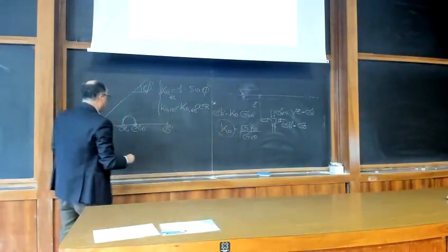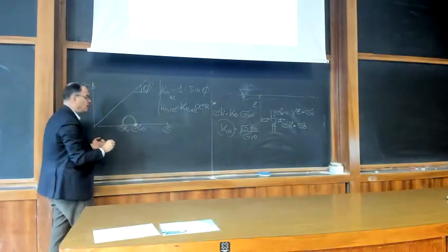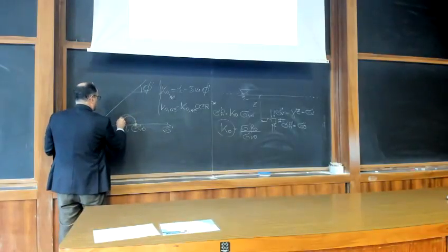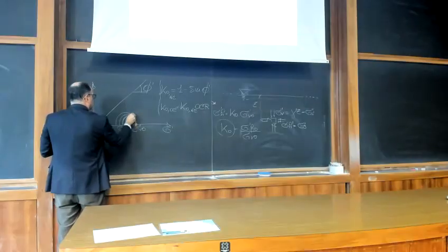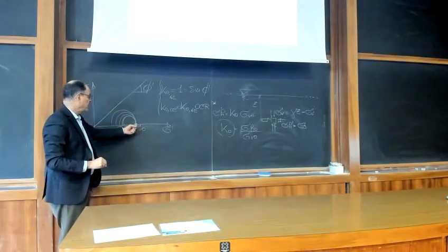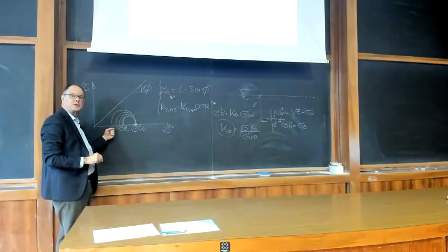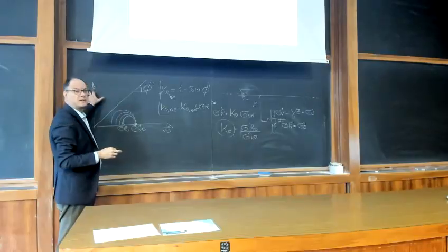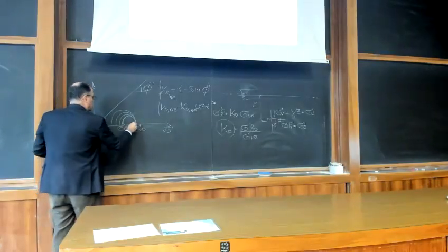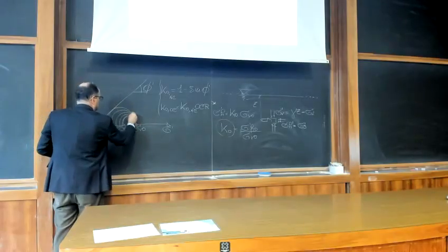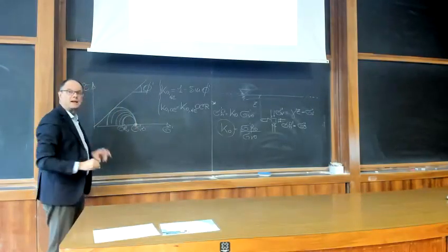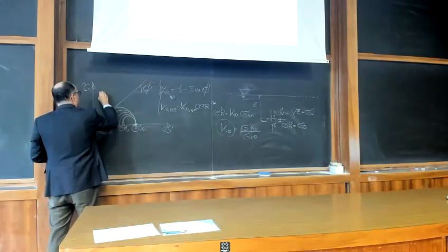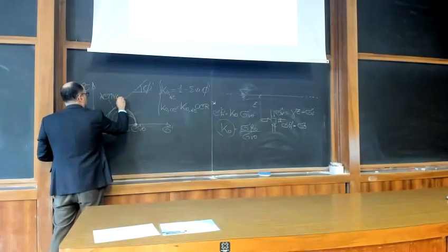In the first case, you can keep constant the vertical stress, and you can reduce the horizontal stress. Okay, so you can have something like that. You see that if you keep constant one principal stress, and you reduce the other principal stress, you make a Mohr circle greater. So you also increase the associated tangential stresses. And you can reduce your horizontal stress until you get to your limit circle. And in that case, we have defined this sigma A, because this is your active stress state condition.